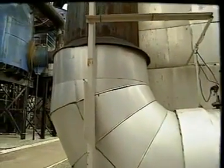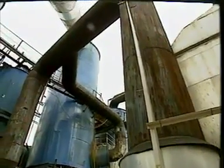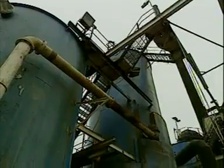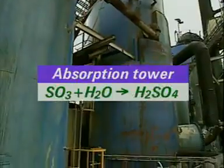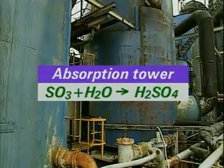After the third catalyst bed, the gas stream is led into the bottom of an absorption tower packed with ceramic material. The rising gas meets a stream of hot sulfuric acid that runs down the absorber. The sulfur trioxide reacts with the water in the acid to increase the concentration of the acid to about 99%.